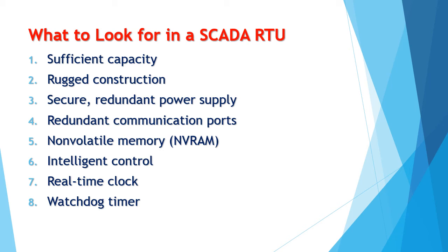Next, intelligent control. Sophisticated SCADA remotes can control local systems by themselves according to programmed responses to sensor inputs. This isn't necessary for every application, but it does come in handy for some users. Next, we have the real-time clock. This is for accurate date and time stamping of reports. And lastly, the watchdog timer. This ensures that the RTU restarts after a power failure.